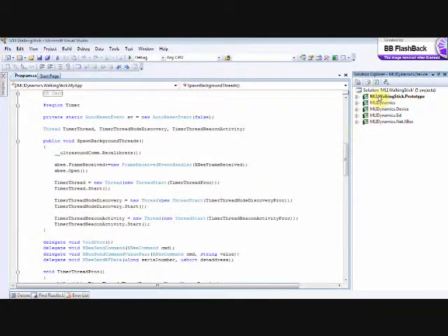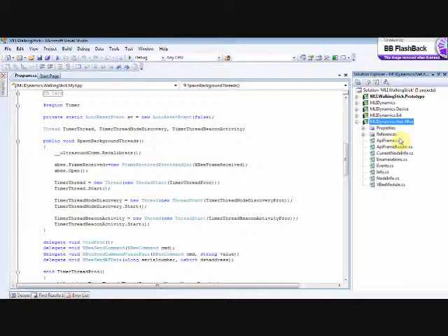So from here you see a couple of projects that I had created to manage this prototype development. One is the walking stick prototype project. Then there's the device drivers library project, and then there's a ZigBee library project. The device drivers are pretty much for the ultrasound ranging unit, MaxBotix EZ1, the accelerometer on the device solutions board, and the SD card device driver. Then there's a library set for the ZigBee XP module, which communicates with it via its API format.